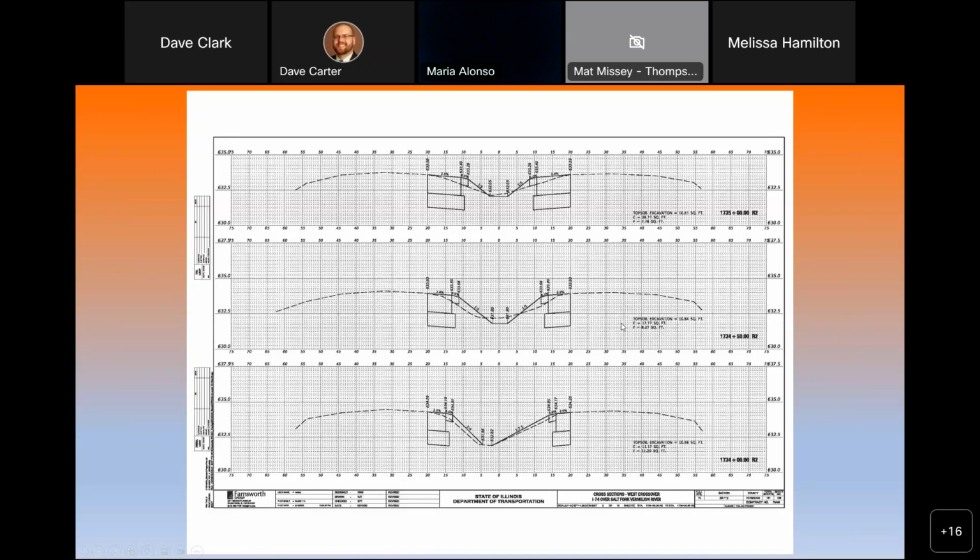Here they show what the topsoil excavation is, how much is being excavated, the earthwork. It has their cuts and fills, and this is what they're using to determine how many cubic yards of excavation and fill and so forth, embankment, there is on a project. A lot of earth moving contractors, some of your larger contractors, will have software that they'll actually go in and plug these numbers in and make sure that the calculation and what's shown on the plans match what they think it's going to be. I mean, everybody makes mistakes.